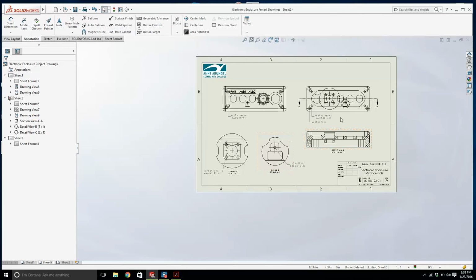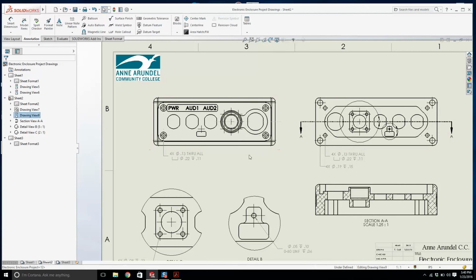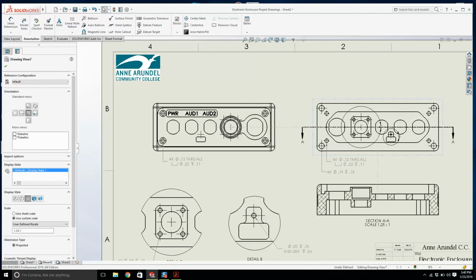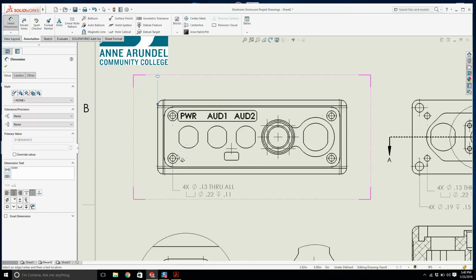Okay. Alright, now in this sheet what I've done is I've been lazy, and I've packed it in with something called ordinate dimensions. Ordinate dimensions are nice because you can pack in a load of dimensions in a small area, but the machinist has to read them. So this is called our ordinate datum line, and everything is related from that. So this is going to be 0, 0. In this type of thing they're nice, it's a pain putting dimensions in, and you can really pack them in. So we go ordinate dimension. This is going to be my 0, 0, and I'm just going to hit these points.